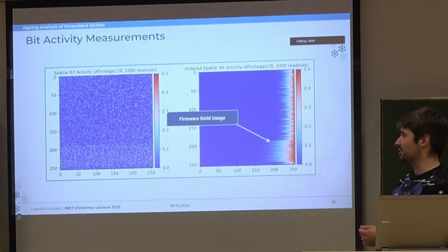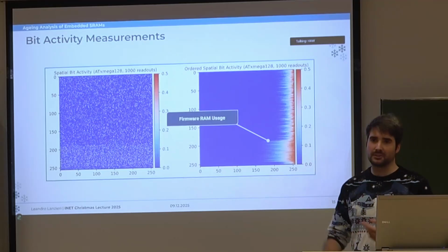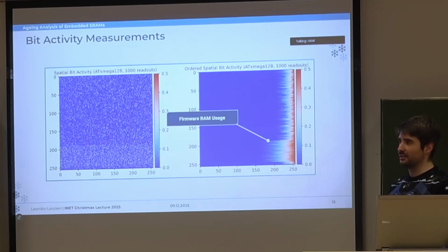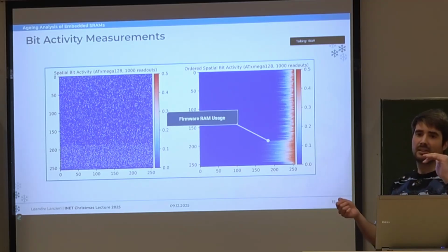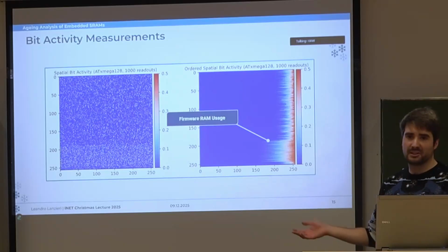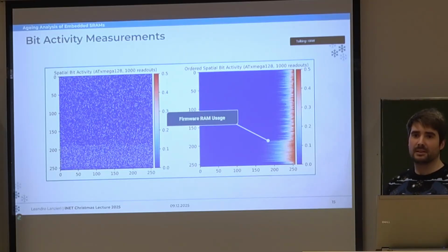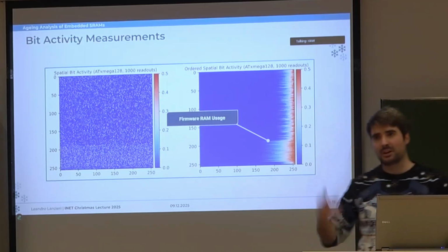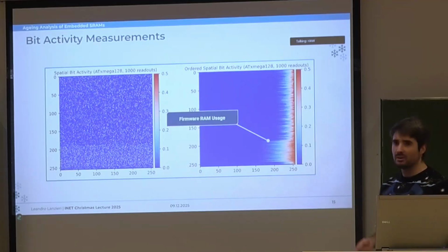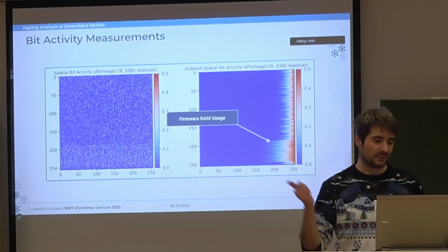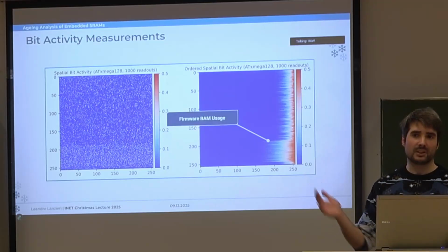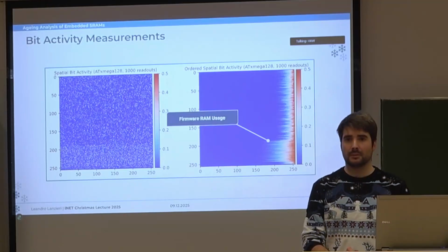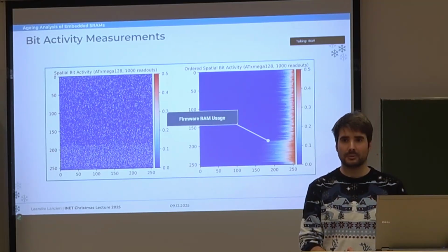There are studies that actually show that for this 6 transistor cell, when the threshold voltage is just too high, then just a slight hit of a big particle, let's say, would flip the bit. That has been studied, and that's a fact. It also happens in the other direction. If the threshold voltage is too low, then it might happen that the transistor is actually latched up. That also happens due to radiation. That happens in space, for instance. That's common in these kinds of devices.